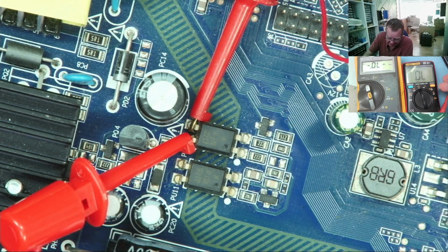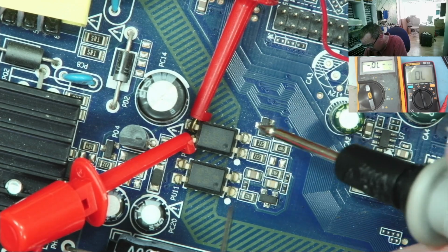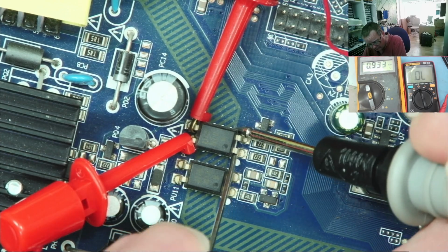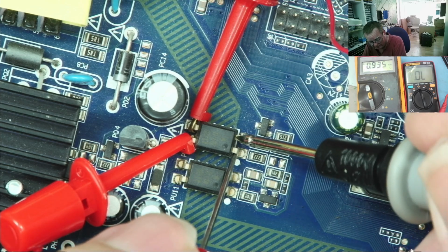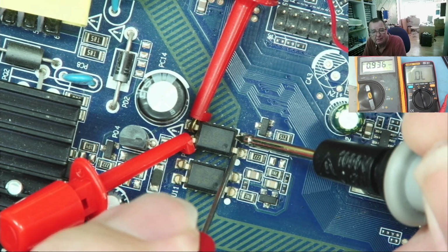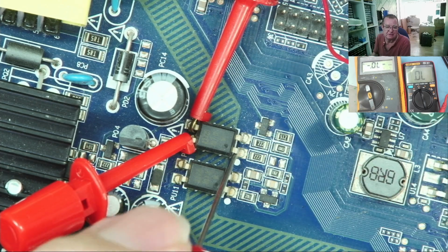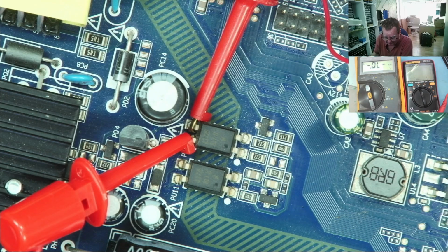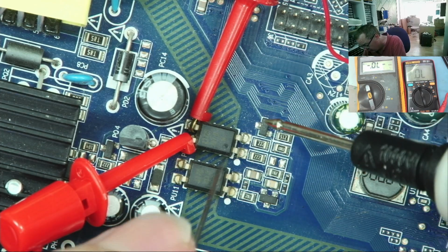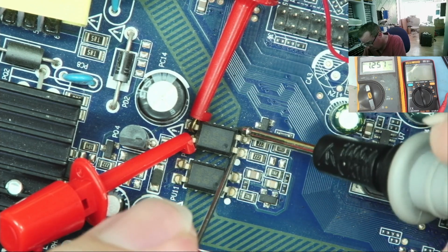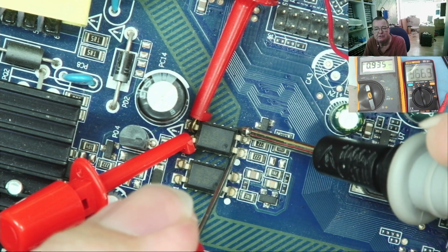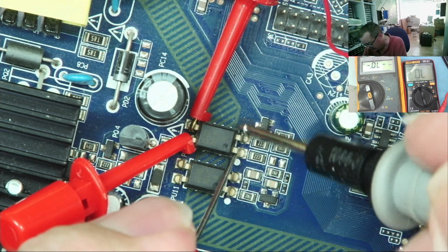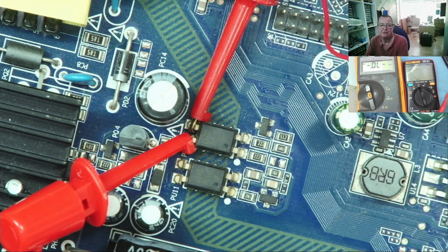You may do this in diode mode as well. It depends a little bit on the opto isolator. Let's see. In this case, it didn't actually do it. I can only assume that's because it's not turning the transistor fully on. It's not on enough to actually conduct, but it's on enough to read a lower resistance. Okay, we'll go back into ohms range again. Let's go for it. And there you go. So you can see we can switch the opto isolator on and we get a very good indication that it's working.